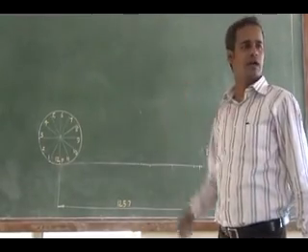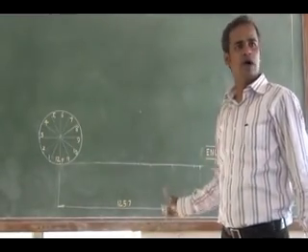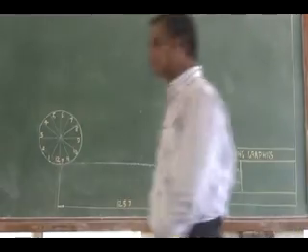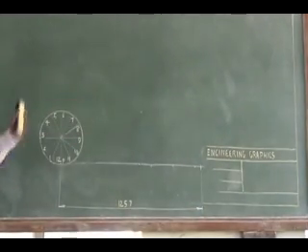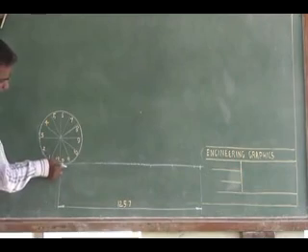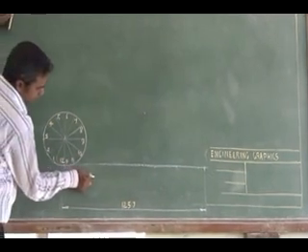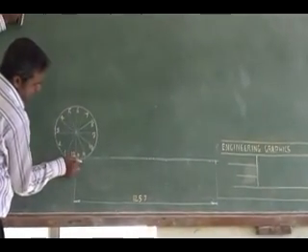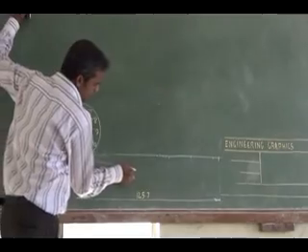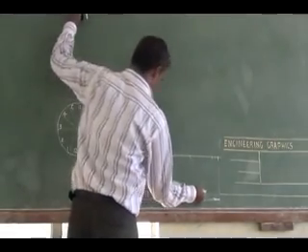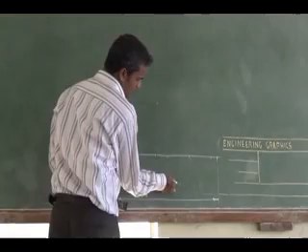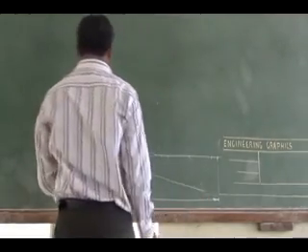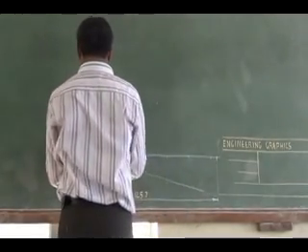Otherwise, you follow the construction procedure. You have to follow the construction procedure, draw a slant line, and get the 12 segments in this one. Use your drafter from any angle, and get 12 divisions.